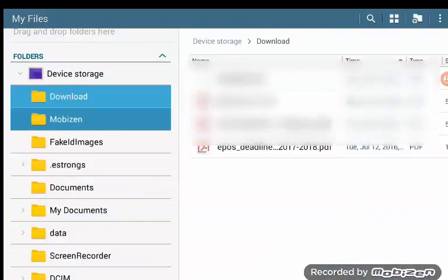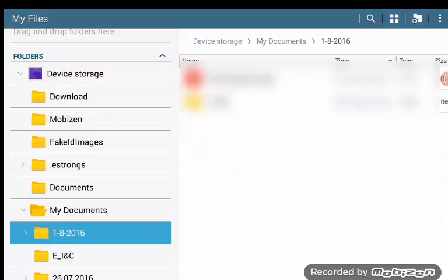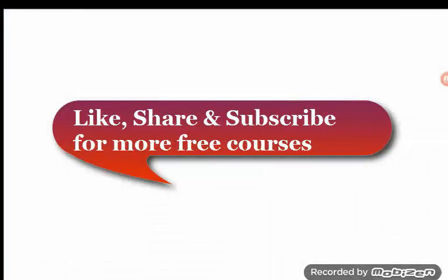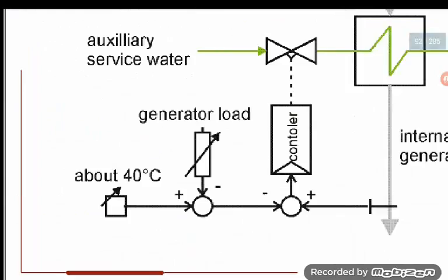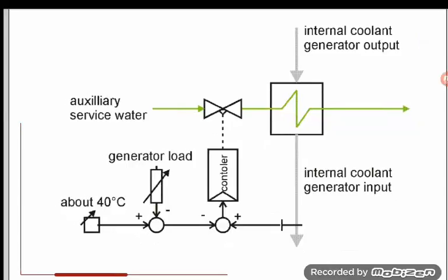Serve water, which the water flow is controlled by this control valve. So when this valve opens or closes, then you change the water flow inside of the omega cooler, and when you have more water flow, you have better cooling. Lower water flow means worse cooling.